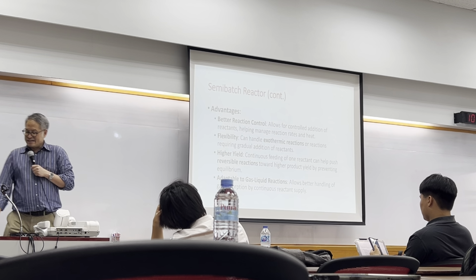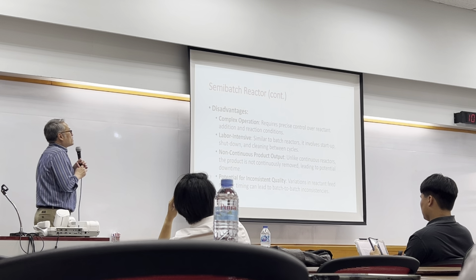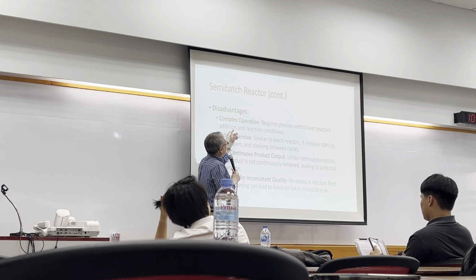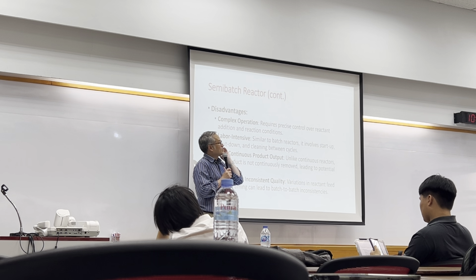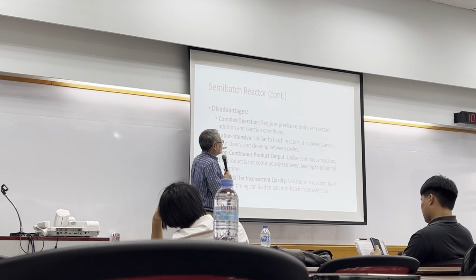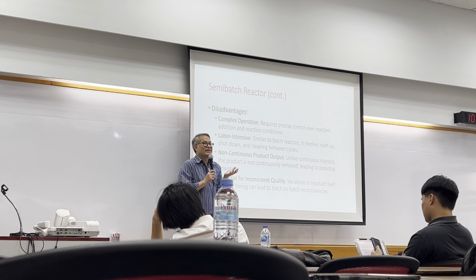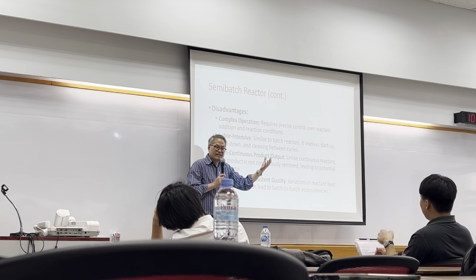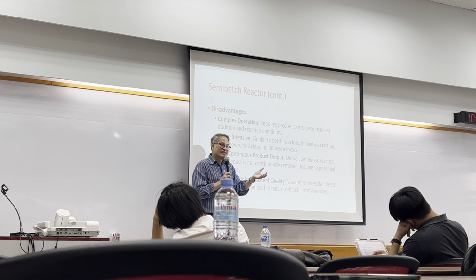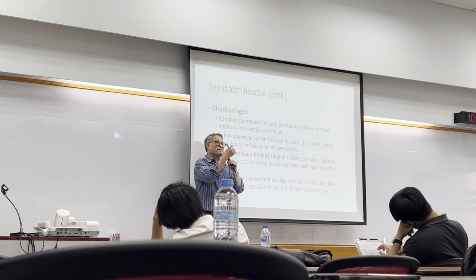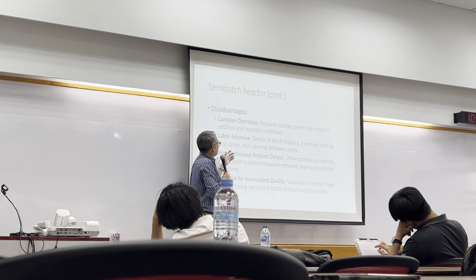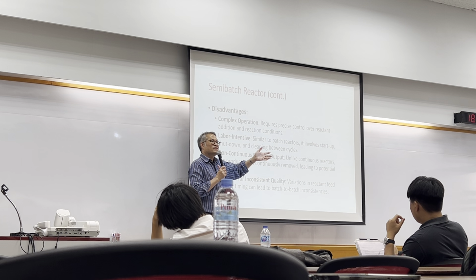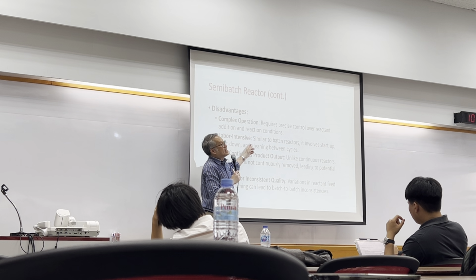What's the disadvantage? Complex operation, because we need good control of the reactant addition and reaction conditions. Labor intensive because it's kind of a batch reactor. There will be startup, where you load something inside the tank and start the reaction by maybe adding something else, and then there will be a shutdown after you reach the final conversion that you want, and then there's cleaning between cycles.